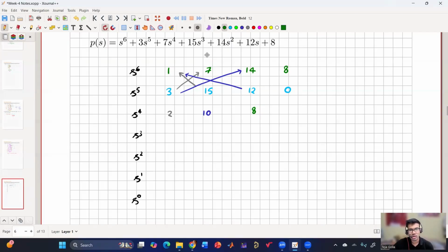Okay. So now let us consider s cube, in a different color, orange, for the rows. What will be the first element? 2 into 15 minus 10 into 3 by 2? 0. So we might think that because it is 0, it will come under the special case that we have solved before, and we'll replace it with epsilon. But we cannot take the decision until we finish the entire row. So now coming to the other element, what will it be? 2 into 12 minus 0. Again 0.